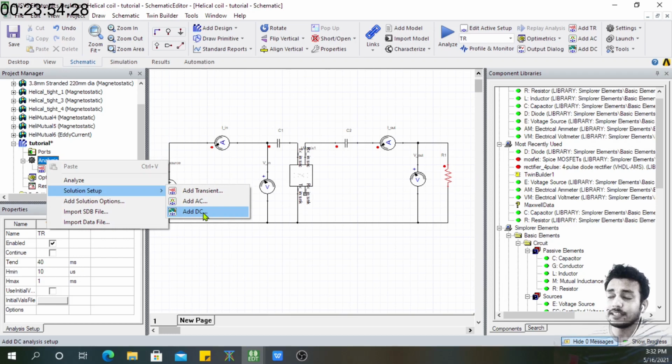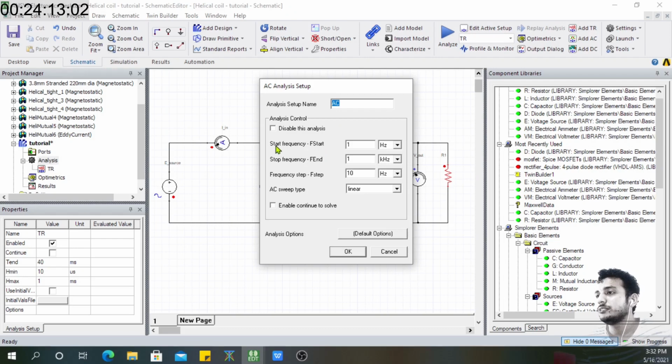It was 37 picofarad. We are going to put the same value in C1 and for C2, the same value will be there, and then we will calculate. So for that we need the AC solution type. So I guess you have understood why we need the AC solution type. Here first you will see start frequency. This is the frequency from where the sweep starts, okay, and stop frequency is the frequency till which the sweeping will happen.